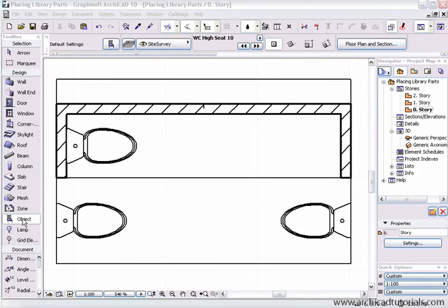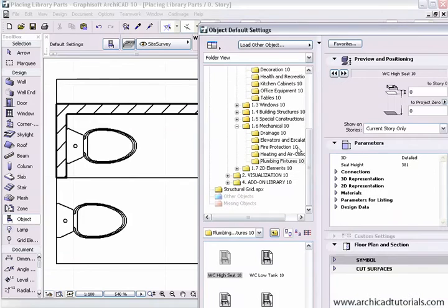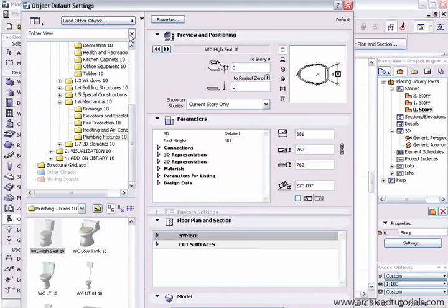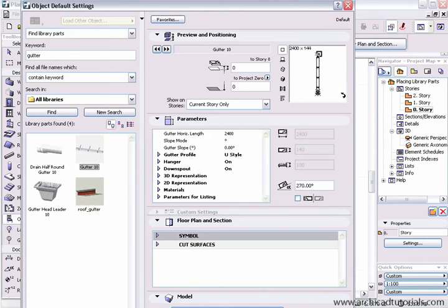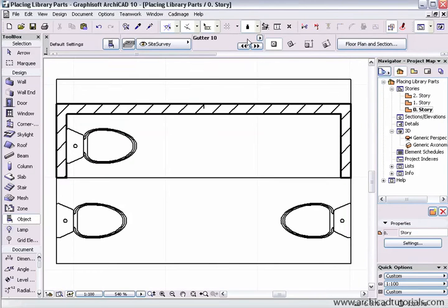The gravity tool can become particularly valuable when you place things on the roof. For example, if I was to look up a gutter, and let's just say we chose this gutter, I'm going to place it around like that. We can change all the parameters if we like, but I'm just going to push OK. Once again, I'm going to place it using this geometry method where I can rotate and stretch as I place, and I'm going to put gravity to roof this time.